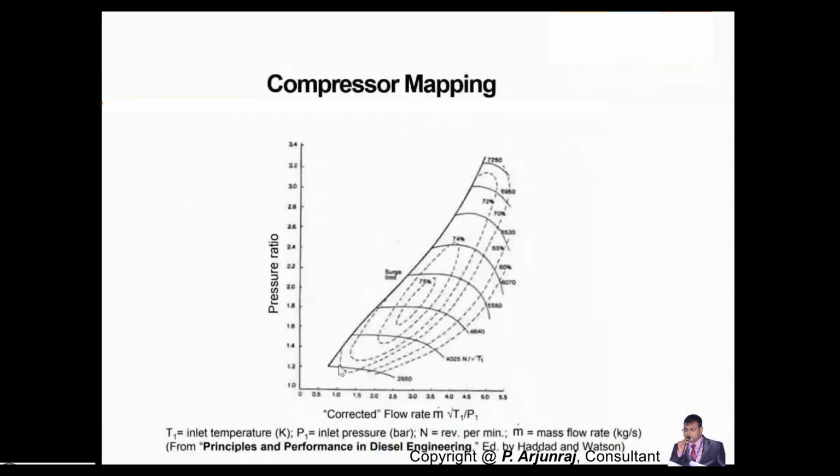And you see here, I told you the turbine RPM will be close to 1 lakh to 1,50,000 RPM, depending upon the speed and then the airflow rate and the mass flow rate of the gas as well. This indicates the RPM of the turbine, and the percentage indicates the efficiency of the compressor. Again, you have a limit called the surge limit. This is the operating threshold limit for